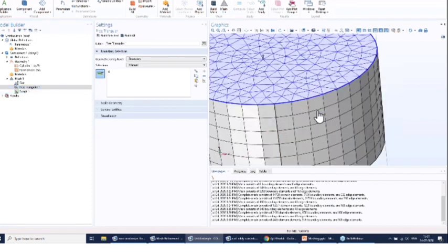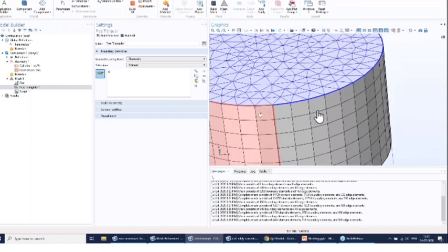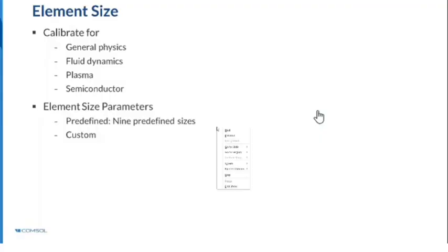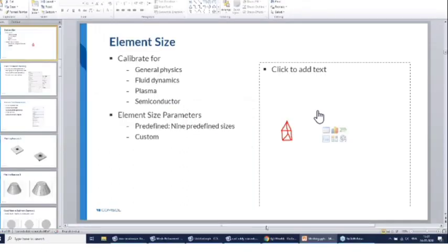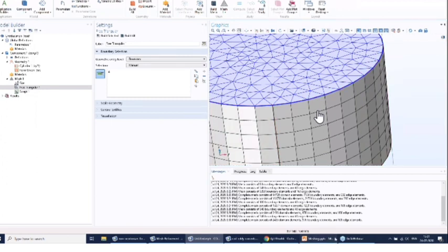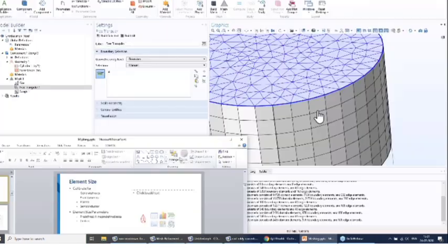Now you can see the kind of elements which are created. If you pay attention, you can see the elements. I told you that they are getting repeated now at each of these surfaces. If you consider one element, you will see that this element looks like a prism element, like this one. There is a triangle like this, and then there are these edges, and on the bottom face also you are getting a triangle. So it looks like a prism element. You can pay attention now onto the geometry here. So it looks like this mesh. I'll just show you.